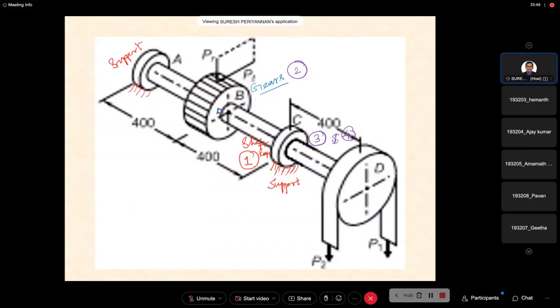That's what we discussed. And while sending the lubricant, how much heat is generated in the bearing? Those things we discuss, I mean the amount of heat generation. How much heat is increased, not generated, increased due to the friction between the bearing and the bush surface, right? Then based on the temperature increment, we can define the lubricant type.